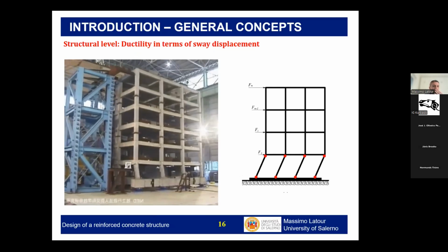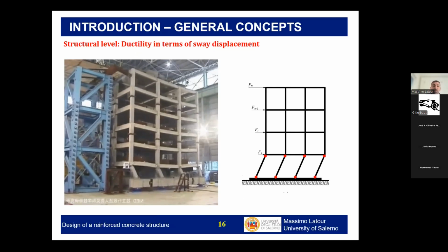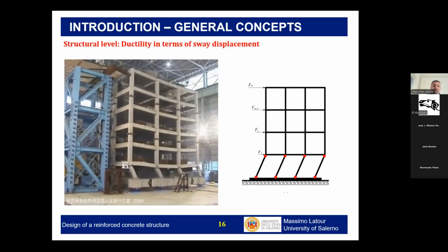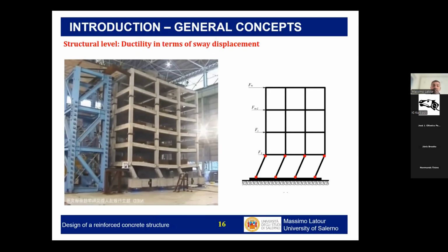Okay, sorry, now it's running. Okay, so this is a failure mode that is very typical of buildings which are not designed compliant to a seismic code, or buildings which have irregular placement of the claddings. So in the past, of course, it was frequently found in the design to have masonry claddings in all the stories, but having a free space at the base of the building.